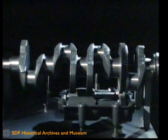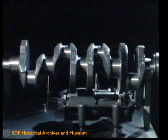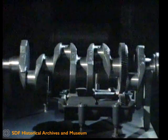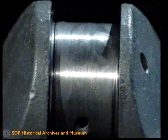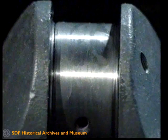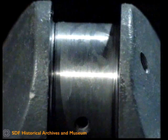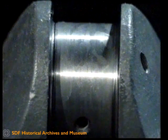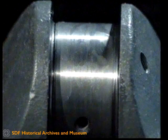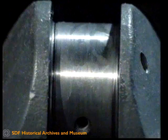In the mechanical parts, high stresses always exist in conjunction with sudden variations in shape, giving a concentration of tensions which can cause cracks and fractures. In order to avoid this nuisance, circular discharge grooves have been worked into the joint profiles of all the crankshafts on the latest series of engines, which drastically reduce such tensions. The rolling process used for creating the discharge grooves provides advantageous surface hardening.